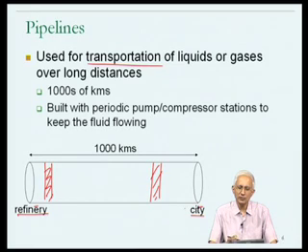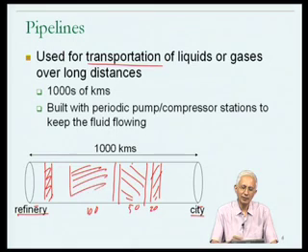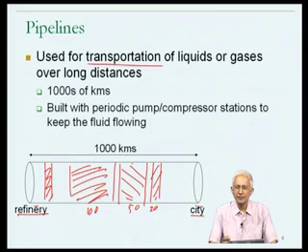A much more effective use of the pipeline might be that after having pumped the 20 kilometers of airline fuel, I conceivably have to leave a little bit of a gap, but I could then pump maybe 50 kilometers of some other fluid, maybe diesel, through the same pipeline. And after maybe a little bit of a gap, I could pump maybe 100 kilometers of some other fraction of petroleum. And in essence, by trying to keep the pipeline full, I'll be increasing the utilization of the pipeline. And in fact, I'll be reducing the amount of time that it takes for any one of these fractions to reach, if I look at the average amount of time across all of the fractions.